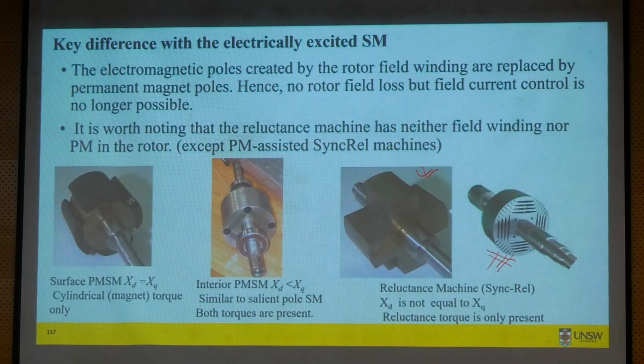So if we directly use a rotor like this, replacing the rotor of an induction motor or a synchronous motor with a simple rotor made of only steel, yes, it can work, but you may have very high vibrations. So to prevent those types of problems, a new type of rotor was developed for synchronous reluctance motors.